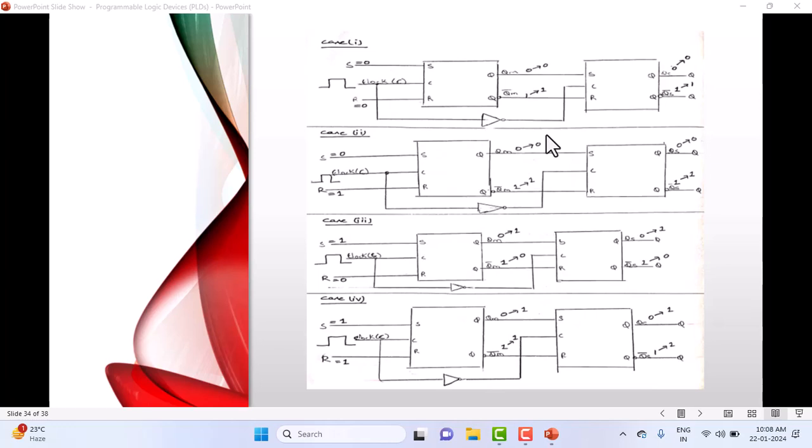The slave becomes enabled now here. And for the slave, this will be the input now, 0 and 1. For 0 and 1, again the output of this will be 0 and 1 only. Clear to all of you? Okay? Any questions for 0, 0? This is what we summarized in the truth table. No change state is nothing but Q plus is equal to Q, Q plus bar is equal to Q bar. Such a state is called no change state.